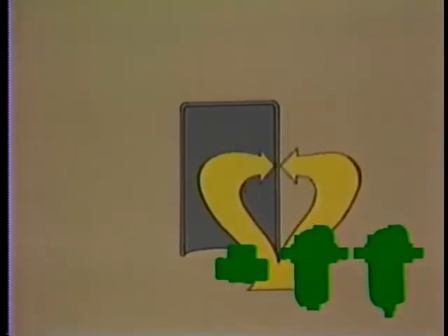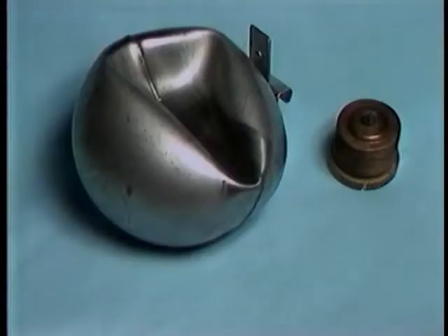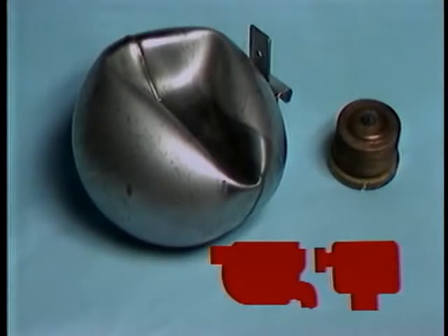The disc trap has no parts which can fail from this sort of shock. The IB and DC traps use open floats with the same internal and external pressures, making these resistant to water hammer. The same cannot be said for bellows or F&T traps, however. The fixed internal pressures in the float and bellows elements make them likely to collapse when subjected to these pressures.